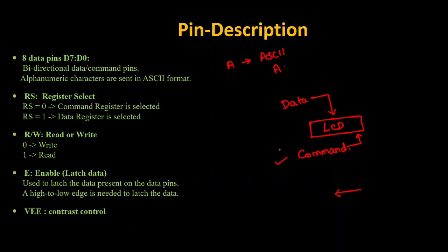So what is getting displayed? It is displayed like a dot matrix, right? So all the characters to be displayed are given through the data register. Whenever a command is given, it is taken from the command register. Whenever you give data, it is taken care of by your data register. Read bar write, we have already seen many things with respect to read bar write, whether it is going to read or write data.